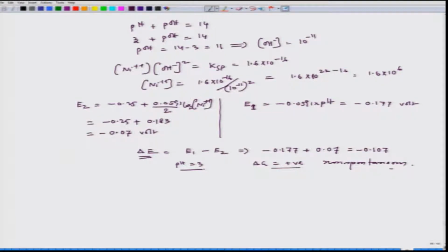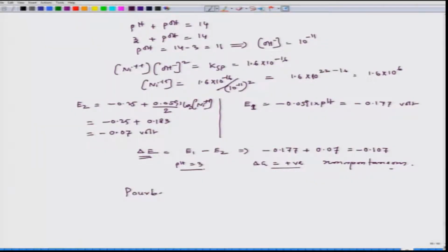but instead of doing these entire calculations to see whether the del G becomes negative for a particular corrosion process, we can also have another route to understand whether the metal would corrode in the water system or not, when it is dipped in aqueous medium with a certain pH level. That information can be obtained from a particular diagram which is called the Pourbaix diagram. This Pourbaix diagram is nothing but a plot between pH and potential.